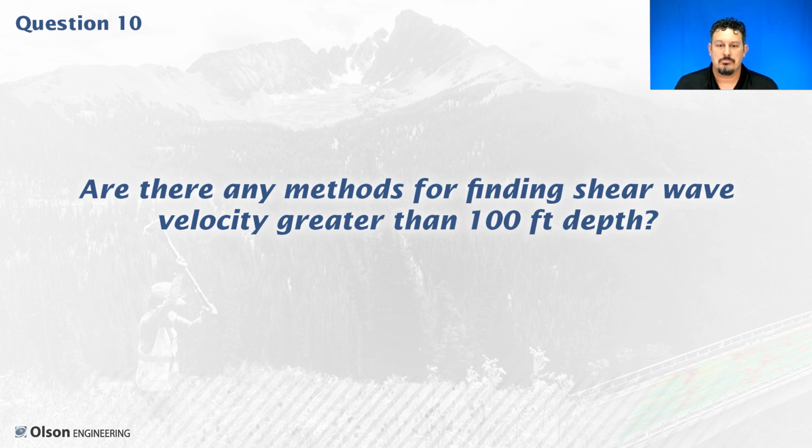Are there any methods for finding shear wave velocity greater than 100-foot depth? You can do MASW surveys. They can sometimes be deeper than 100 feet, and you can do shear wave refraction tomography. It just depends on the site. For engineering, 100 feet is sort of that magical cutoff, so that's typically what we're targeting. And the requirement for the International Building Code for a VS30 or VS100 is a 100-foot depth requirement.